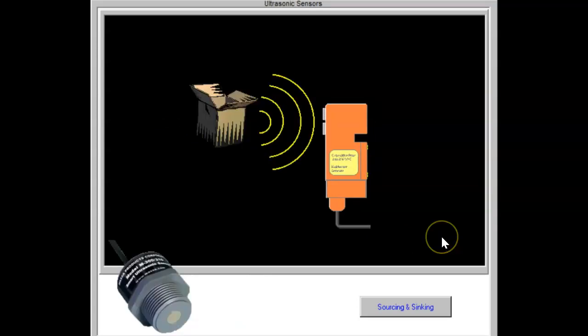Ultrasonic sensors operate by emitting a pulse of high-frequency sound and then detecting the echo when it bounces off the target object. These sensors may be used to determine distance to the target by measuring the time interval between the emission of the pulse and the return of the echo. Many of these sensors put out an analog output voltage signal. The value of this signal determines the distance to the object target.